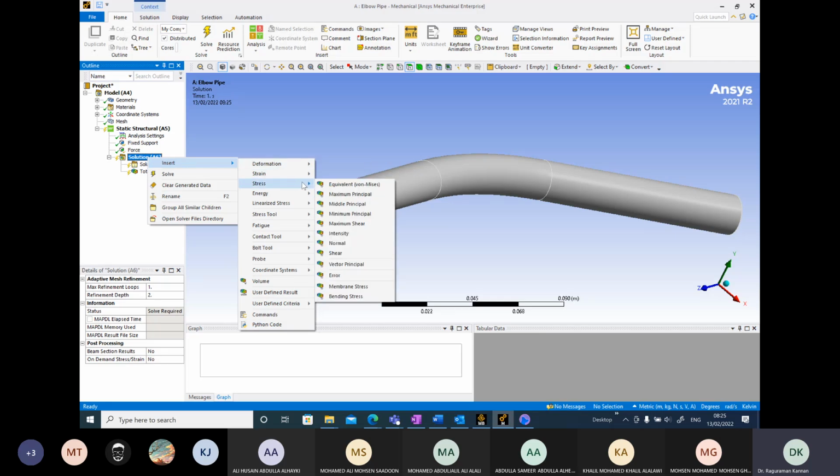We want some information about stress. Since this is a 3D problem, you will have several stress components. If you have taken my solid mechanics course, you will know that there are 6 independent components, but you can combine these 6 independent components and come up with a single value for stress, which is called the equivalent stress. In finite element analysis, you will always come across the von Mises or equivalent stress. This stress determines whether failure will take place for a given material or not.